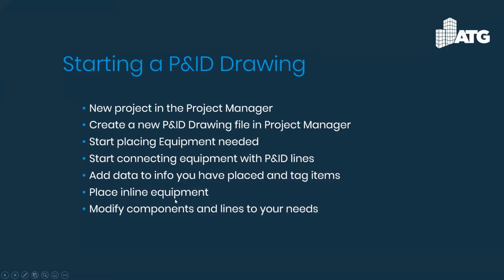We can go in and place some inline equipment, valve type information. And then we can go in and modify components, line work to our needs. Sometimes you need to adjust your P&IDs to allow a little bit more room for placement of additional objects. You don't always have to place all the equipment right at the start. Sometimes you don't always know what you're going to place. Sometimes some of that information comes later. Sometimes you need to go in and make some modifications to that.